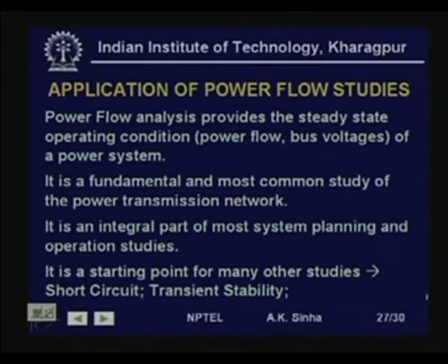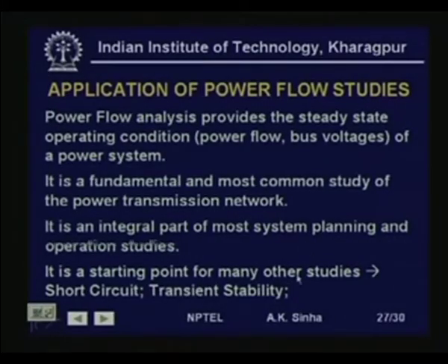Similarly, for transient stability, we are talking about the dynamics of the system. If a fault occurs, how are the generator dynamics going to behave? If we want to do this study, we do it by using transient stability analysis. Now, this transient stability study also requires a power flow study as a starting point, because we have to start from a steady operating condition and then apply a fault or some outages and see how the system dynamics goes on. So, again here we need the power flow study for the initial starting point. It is a starting point for many other studies.